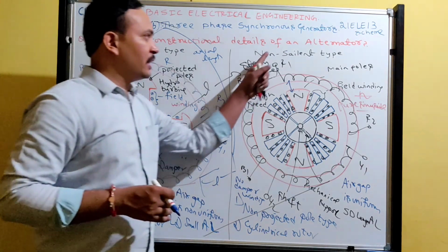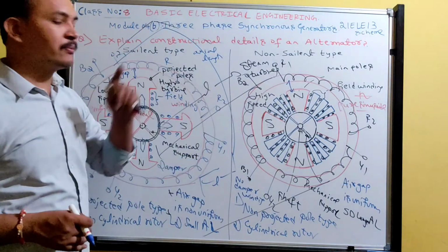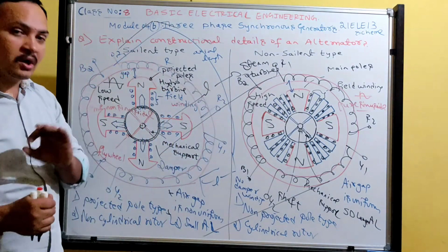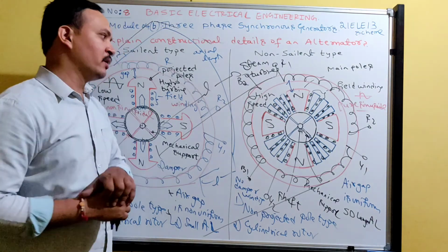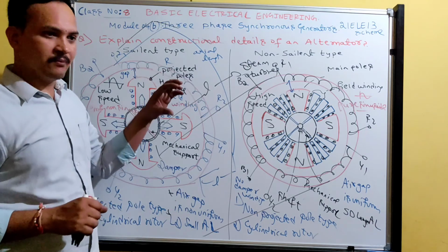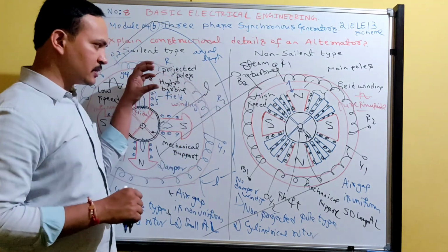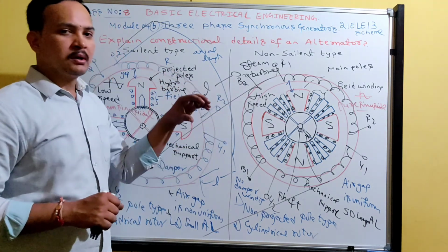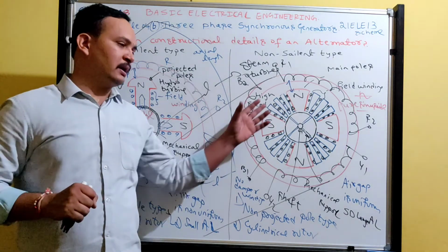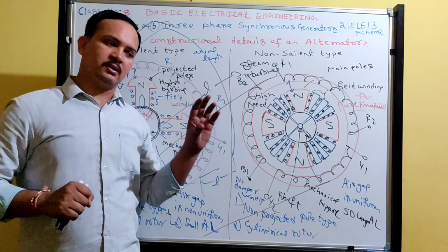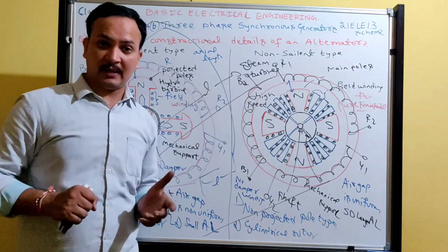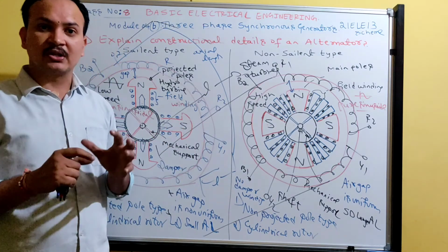But damper winding is not required here. Such vibrations will not occur because we can have strong control on steam flow. We have better controlling strategies for flowing steam to the steam turbines. Steam is passing through the turbine, so we have effective control. However, if the steam pressure is very high, beyond our expectation, then the turbine may fluctuate.